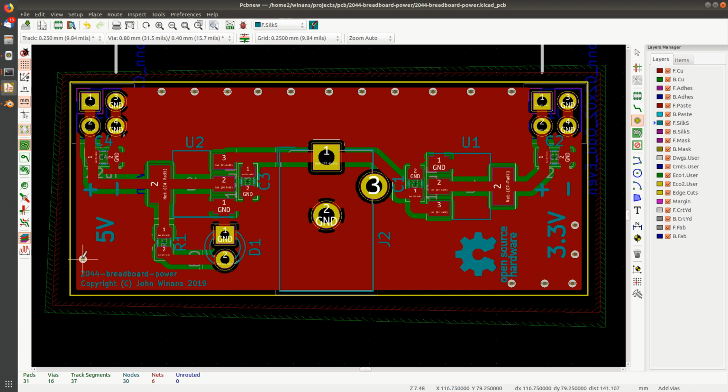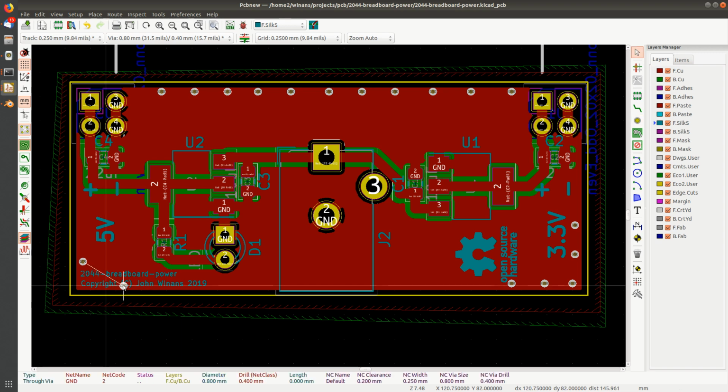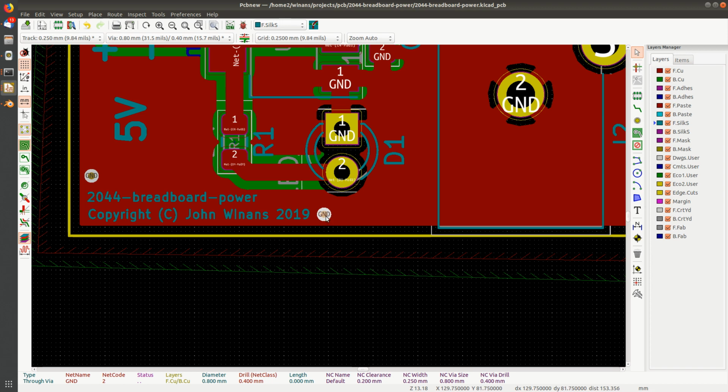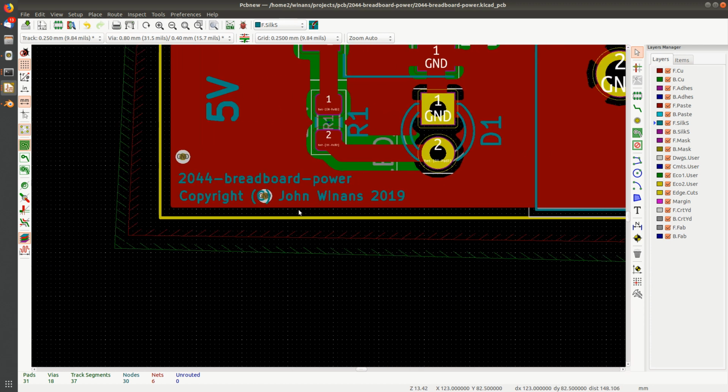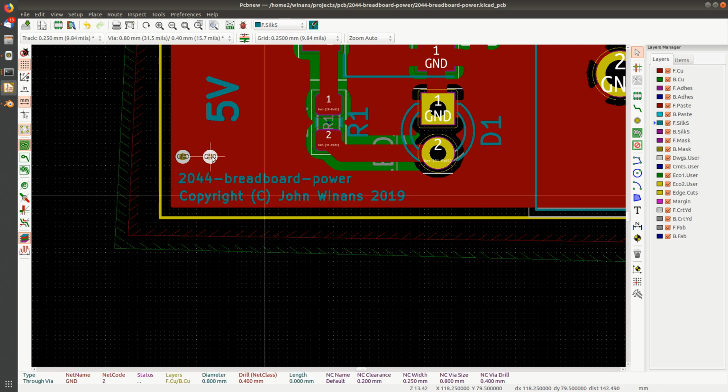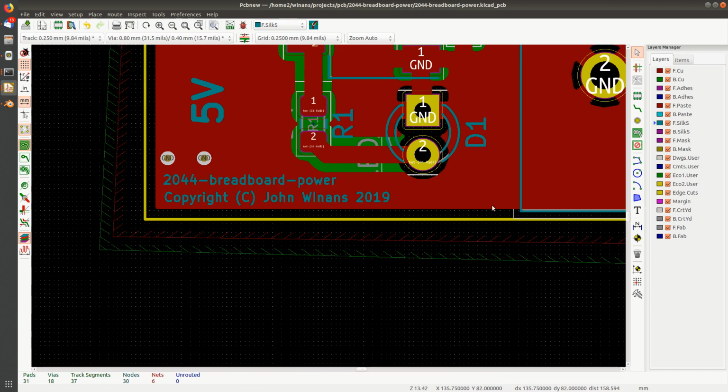Now if you put vias where your text is, like if I put it right there, some vendors will put the text there and you'll be able to see it, other ones won't. I happen to know if you go to OSH Park, I think what they do is they don't put the silkscreen over the via holes, so you wouldn't be able to read it. You could do something like this though. If I moved it and put it like right here, that C would print. It might be that the bracket, if you stuck it like in the middle of an O or something, yeah, it would be fine, if you want to be silly about it or something like that. Anyway, these are not super required anyhow, so not a big deal.